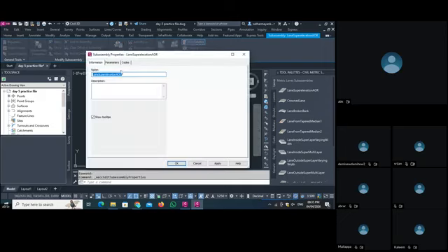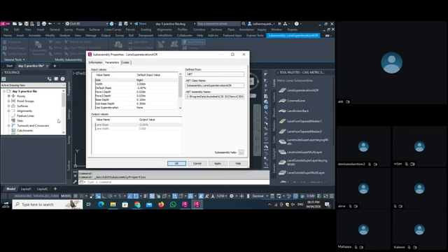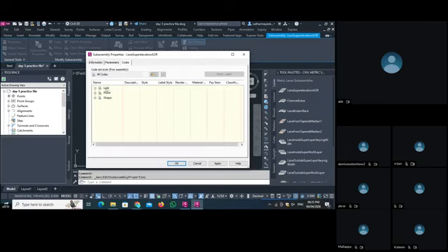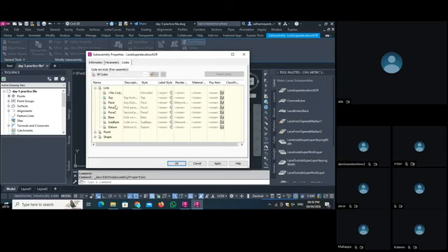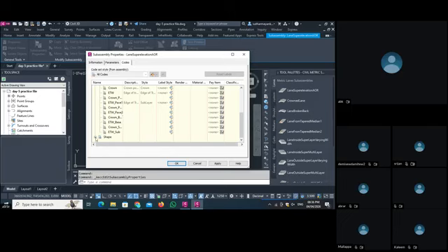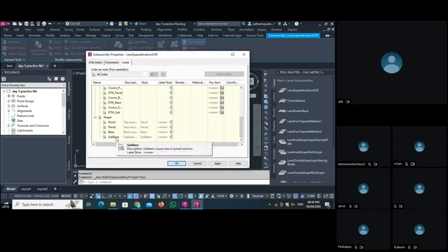Here, if you want to provide a name, you can give the name. Parameters: the parameters we checked in the properties, you can see the same parameters here. Okay, then the codes. In the codes, there are three things: link, point, and shape. If you generate any assembly, these three things are mandatory to insert. See, in the link, they provided all the links for all the layers. In the point, they provided all the points. And in the shape, they provide all the shapes, since there are 4 layers in this sub assembly. So all 4 layer shapes are provided here.